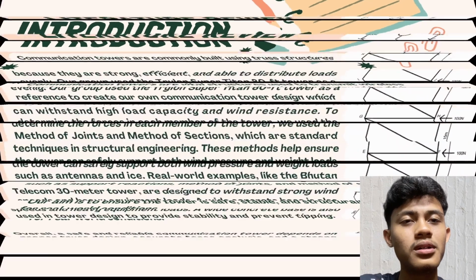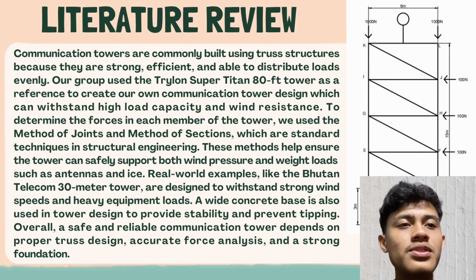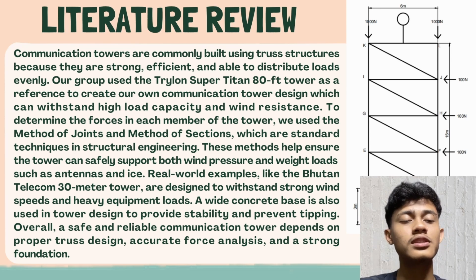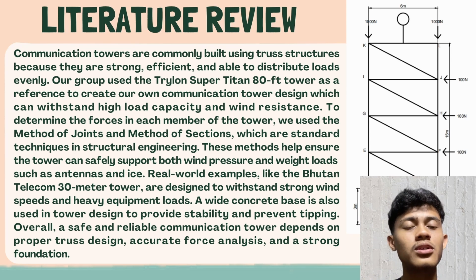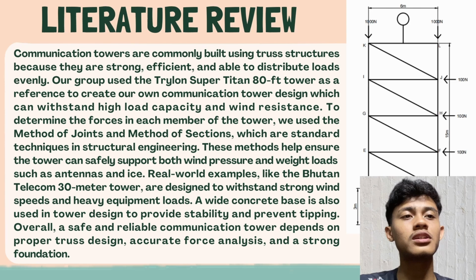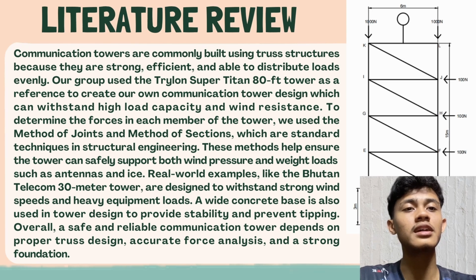Okay, for our group literature review, communication towers are commonly built using truss structures because they are strong, efficient, and able to distribute load evenly. Our group used the Thailand Super Titan 80 feet tower as a reference to create our own communication tower design, which can withstand high load capacity and wind resistance. To determine the force in each member of the tower, we use the method of joints and method of sections, which are standard techniques in structural engineering.